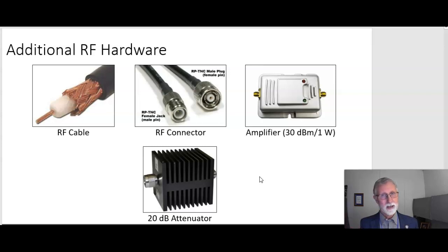It's going to be indoors, it's going to be outdoors. Then I've got to worry about how I'm going to mount it. Then you can look at the antenna pattern, you can look at the antenna gain, saying, okay, this is what this antenna does. This is the shape it does. So based on its shape, then I want to put it at this location. That location means that I have to mount it a certain way, which then leads to mounting decisions.